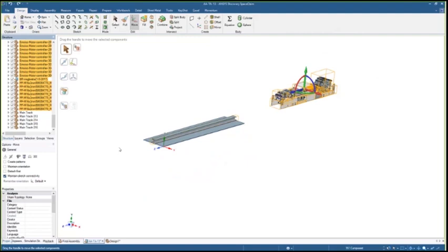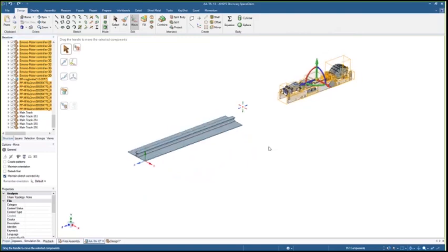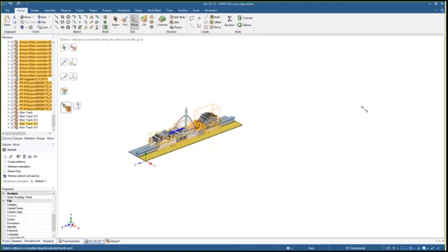And so all of those things are selected, and I want to move them up to the center of the track. So I'm just going to pick that blue direction, pick the up to button, pick a face, and it's going to take 150 bodies and just move that over. Was it SpaceClaim's issue? Was it something in SolidWorks? Is it something not related to either? Who cares? Very easy to go ahead and just make that kind of change.